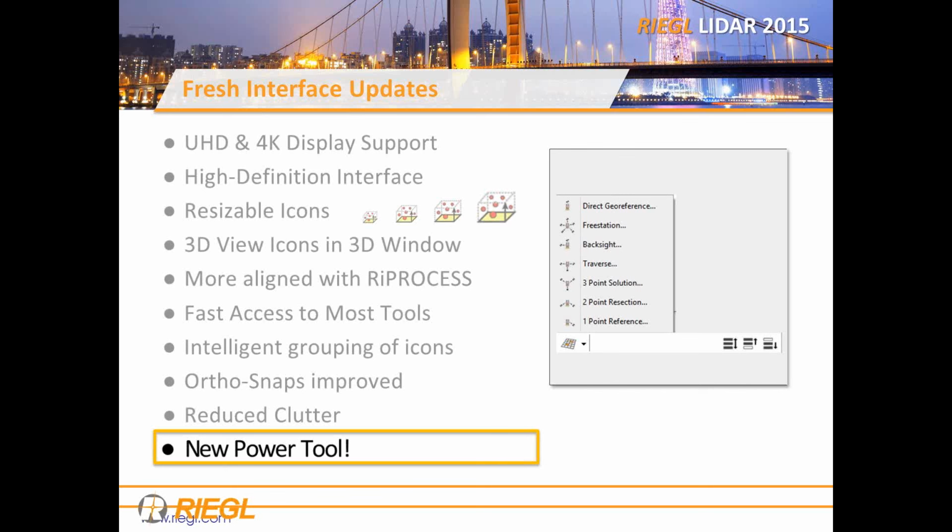Yeah, so the terrain filter, you saw me selecting an area that has the ground and the vehicle, yeah? So what the software does is that it uses an algorithm to detect the first set of points that are on the ground, which is considered a plane. It doesn't create a plane, but it considers the first set of points on the ground as a plane. Then everything else above the ground is considered noise. Now, noise could be anything. It could be a car, a person, a gun laying on the ground, so that can also be noise. So that's as simple as that. And it's completely automated, so you don't have to do anything. All the terrain filter settings are preset from when we release the software.